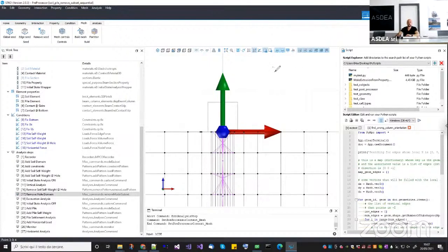Imagine this one is my beam. I have 2 nodes, and then here my solid at the same location. Now this node here is connected with the nearest element. So I'm saying that this one is the slave and these 2 are the masters. Now if they share the same coordinates, it may happen that due to round-off error, this one might be at a small tolerance below the minimum coordinate of the pile.